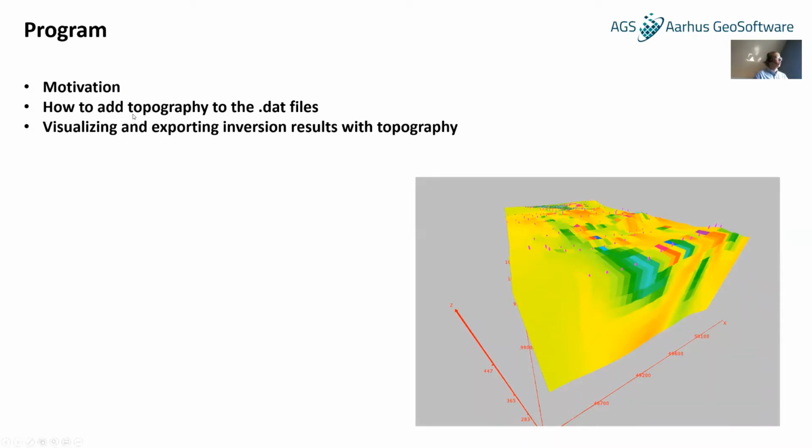Then I'll show how to add topography to the Res3DInv DAT files. And finally, I will talk about how you can visualize and export the inversion results once inversions have been run with topography.